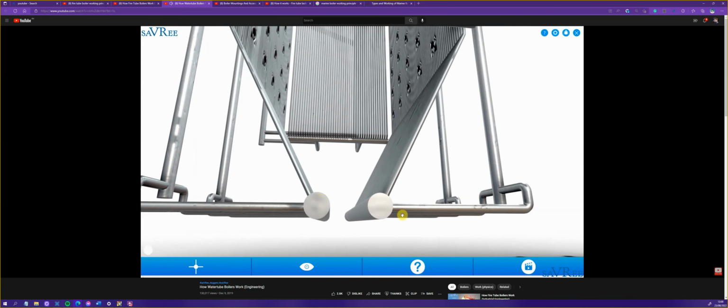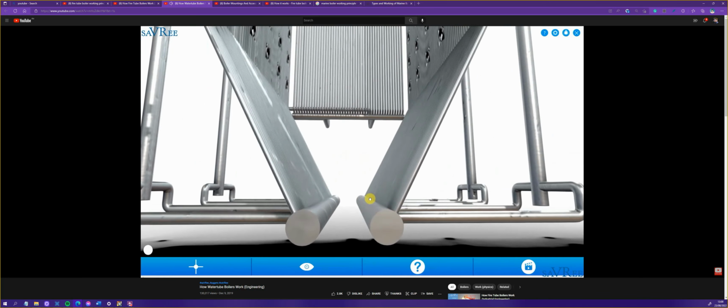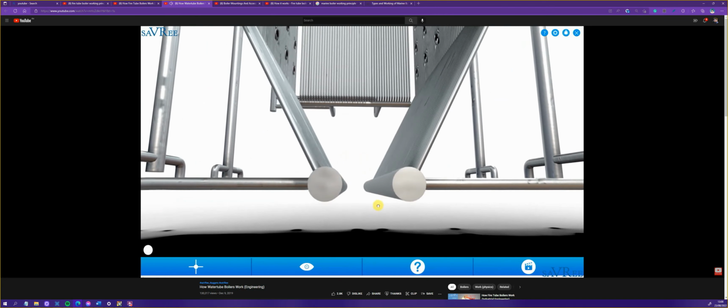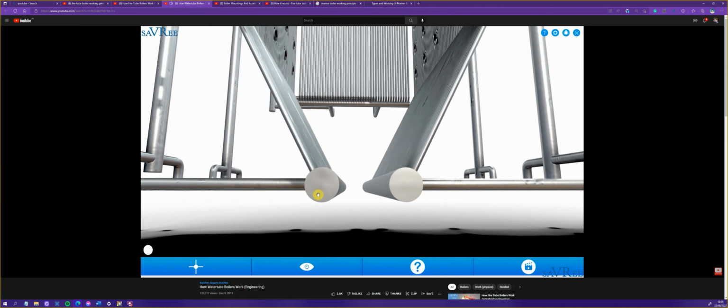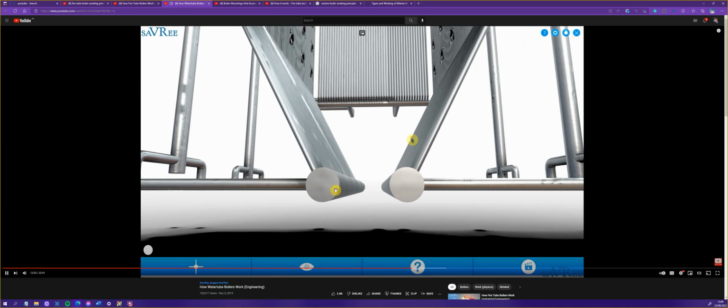We call them mud drums. They're not actually full of mud, it's just that a lot of the sediment and other things that are flowing around inside the water system will tend to accumulate inside these 2 drums, and then occasionally we'll have to open the drums up and remove the contents inside the drums. So we call those mud drums, and the top drum is called...